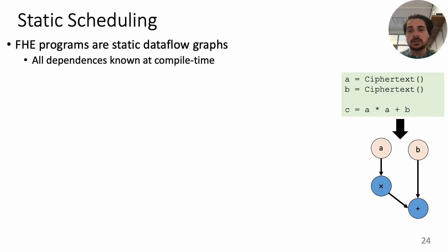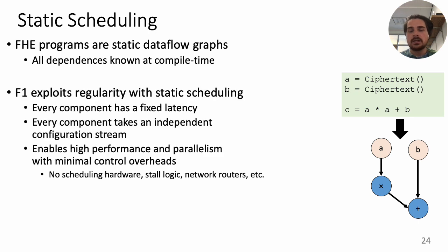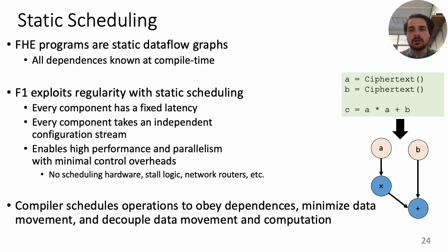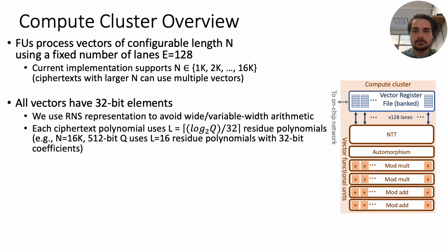We'll now start to discuss some interesting features of F1's design. We designed and implemented a complete software stack that compiles FHE programs expressed in a simple domain-specific language to scheduled F1 instructions. An FHE program written in our DSL precisely describes the data flow graph. Using the fact that we know all data dependencies ahead of time, we can schedule each instruction at a precise cycle. We can also manage our memory hierarchy statically, making sure the data is efficiently fetched ahead of time and replaced using a close approximation of the optimal Belady's MIN algorithm.